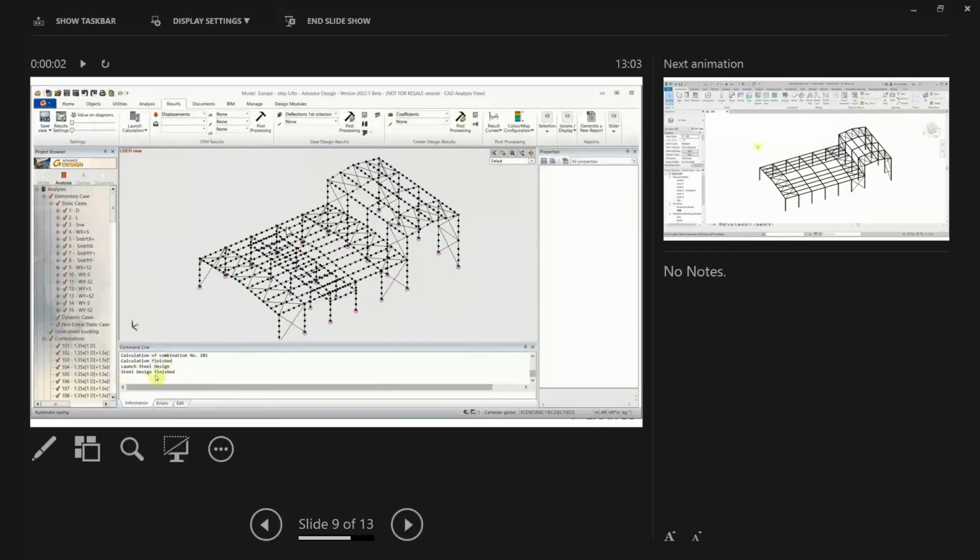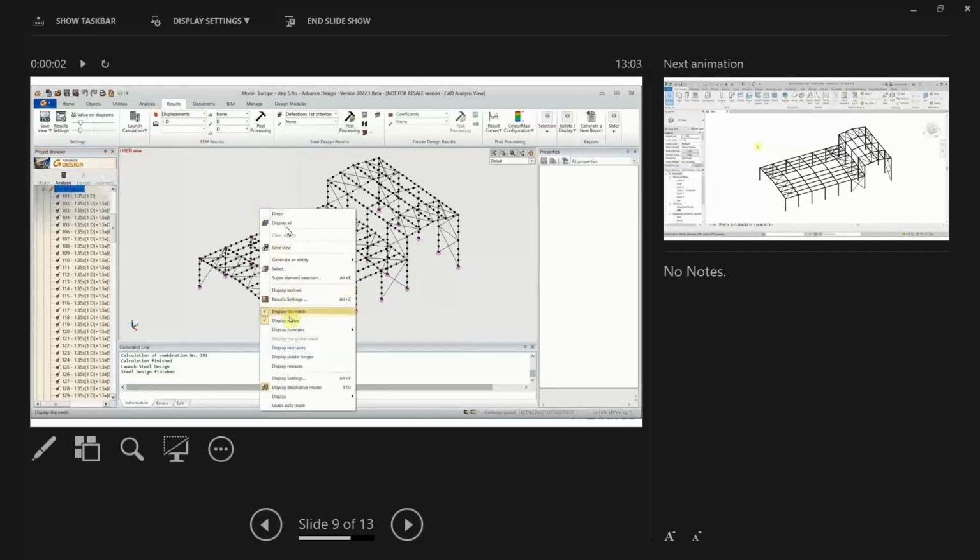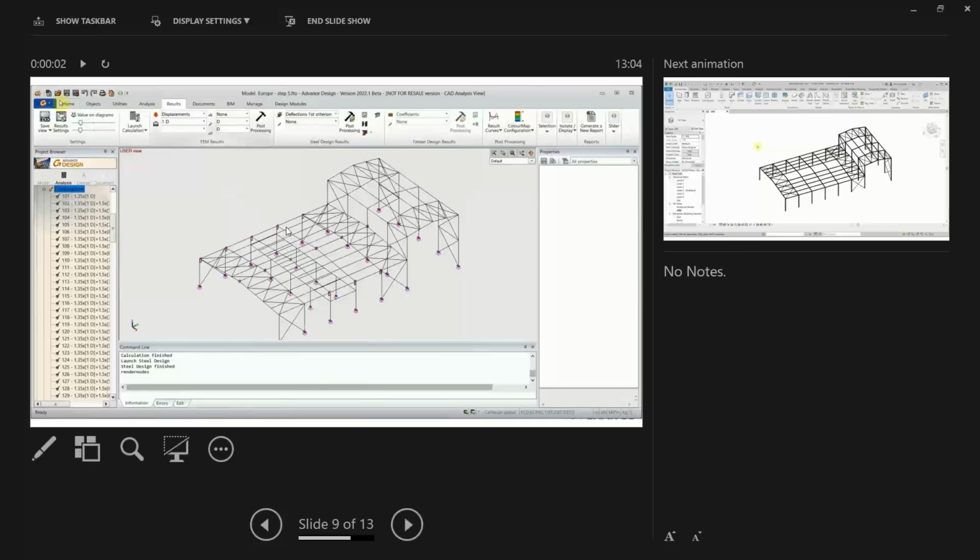In this particular model, for the bracing, you'll notice the bracing hasn't got any meshing, simply because I've set the settings for the bracing to be tension and compression only, so they will not attract any load on them. Specifically compression only, in case you're wondering what's going on. So here we have our FEM results and steel design results. Okay, I'll just turn the nodes off here.